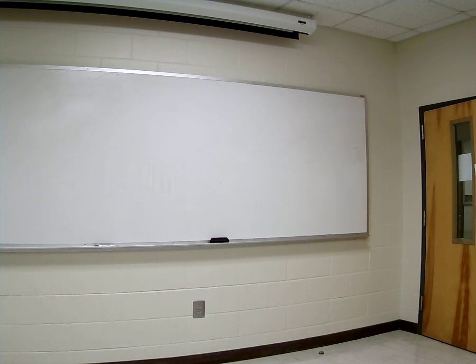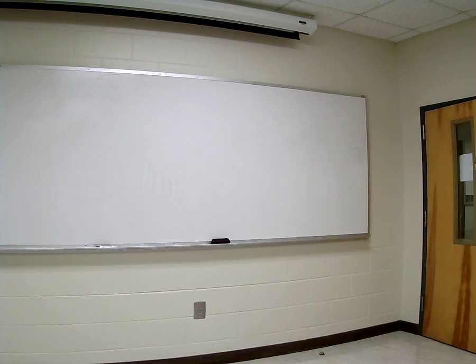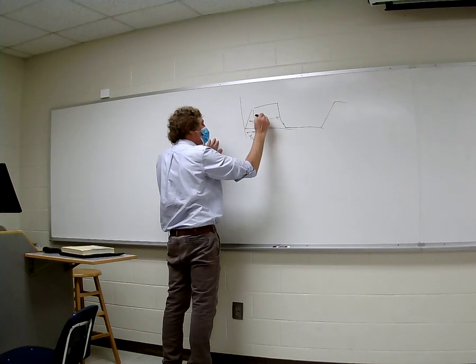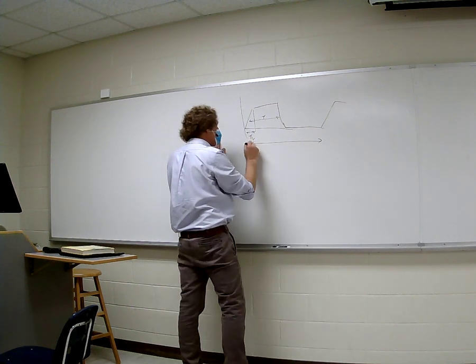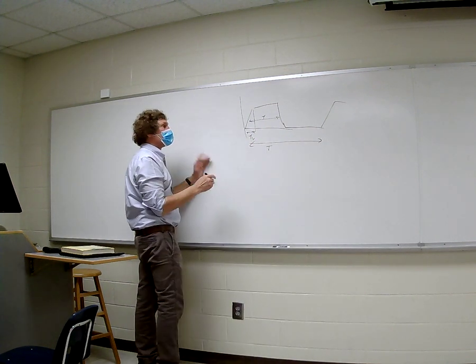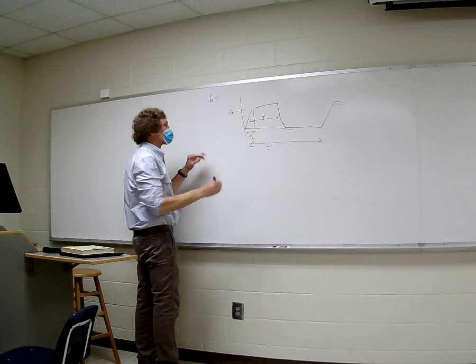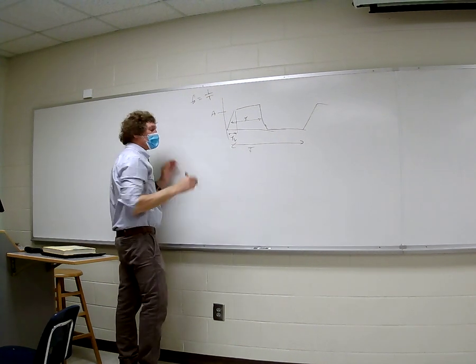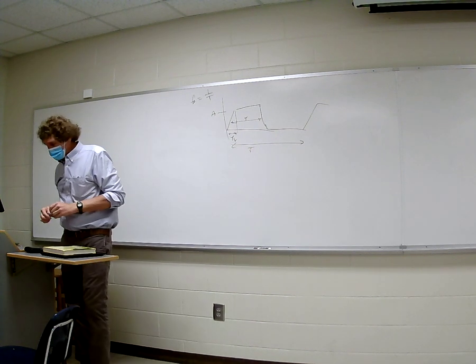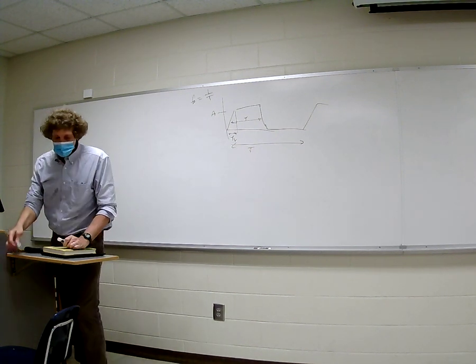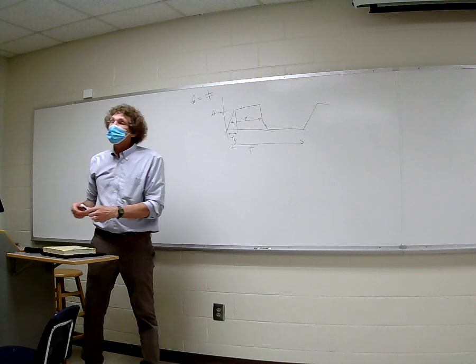Well, first of all, you're going to have a waveform. If you're going to have a waveform, we're going to have something like this. It's repetitive, right? It's a square wave, and we've got a rise time tau rise. We need the on time tau over the period capital T, the duty cycle. We need the magnitude A, and we need the characteristic frequency, the periodic frequency, F naught, which is 1 over T. That would be the actual square wave frequency.